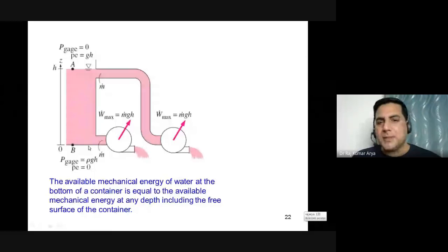Same thing here also. Whether you take the connection from here or here or here, at the same datum level or the same horizontal plane, you will get the same energy level. No matter whether you have the connection from here or here. Getting the point? As far as the positions of the points where you are discharging the fluid are the same, every point will get the same energy, no matter whether you make a hole here or somewhere on the bottom side.